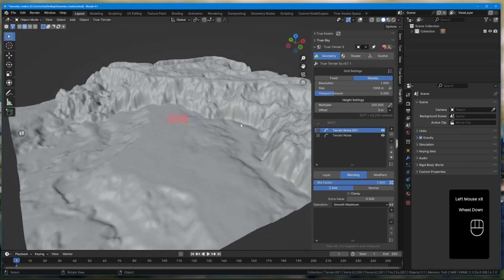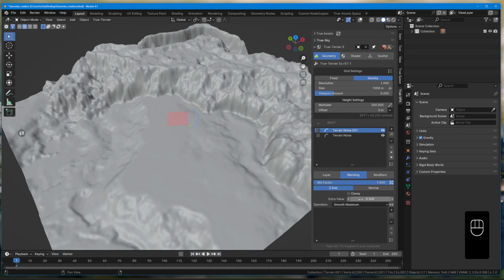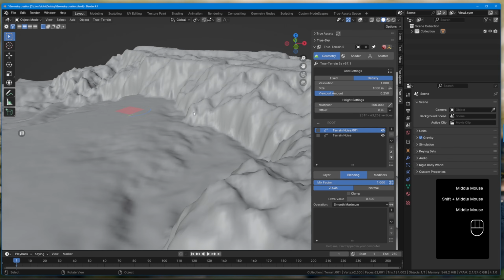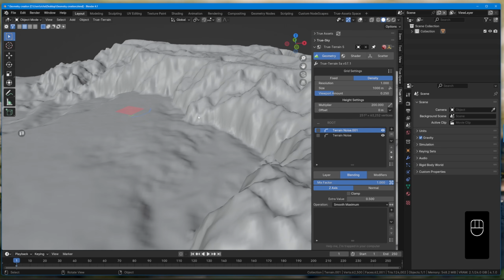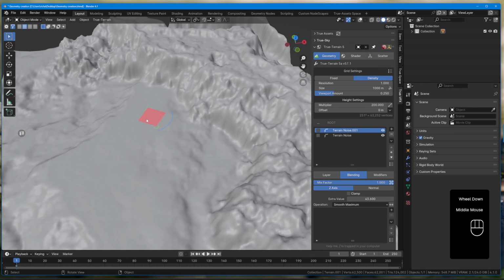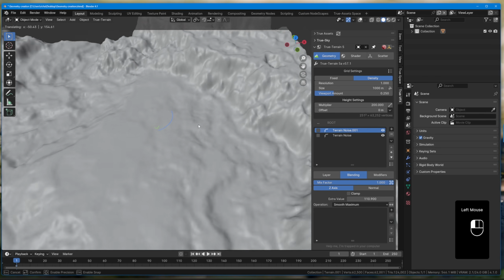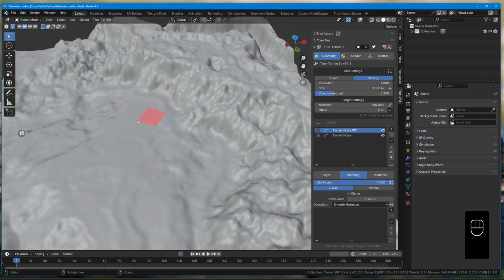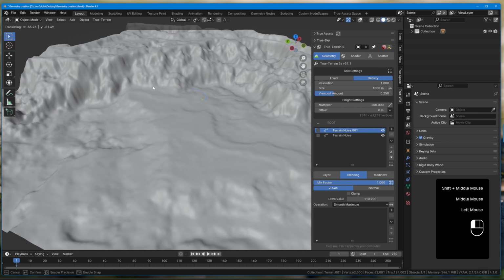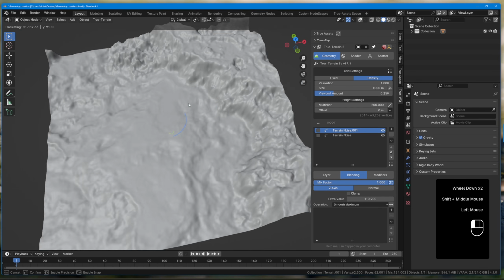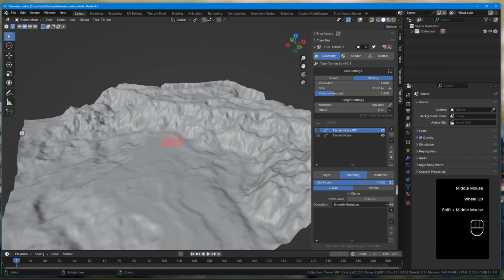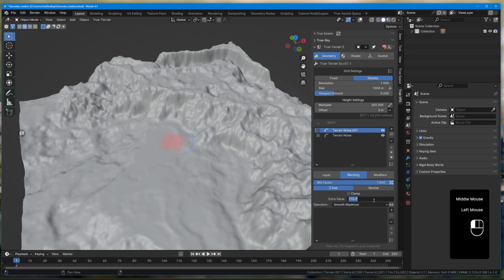In blending, by default, we use a mathematical value. It is smooth maximum, and what this does is it takes the point of the previous layer and maps it to points of a similar value to the other layer and allows you to blend those together with an extra value so that you can blend them seamlessly, and the higher this value is, the smoother that blend is, and the overlap of pixels or faces between those layers becomes less apparent, or more apparent that they're overlapping and less that they're not.